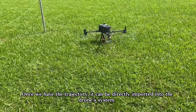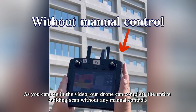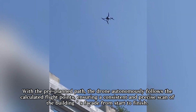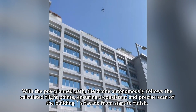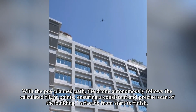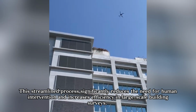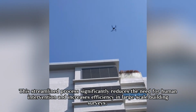Once we have the trajectory, it can be directly imported into the drone system. As you can see in the video, our drone can complete the entire building scan without any manual control. With the pre-planned path, the drone autonomously follows the calculated flight points, ensuring a consistent and precise scan of the building's facade from start to finish. This streamlined process significantly reduces the need for human intervention and increases efficiency in large-scale building surveys.